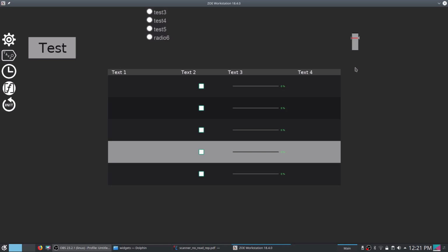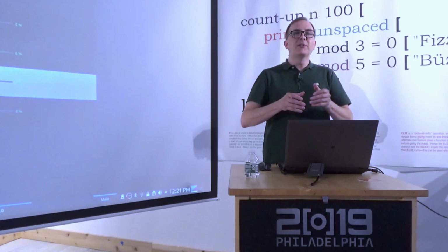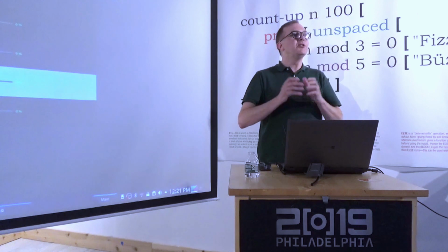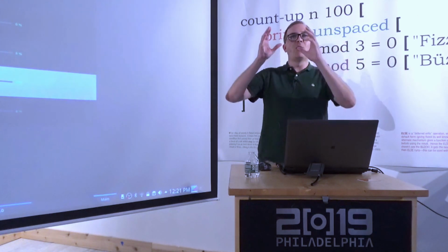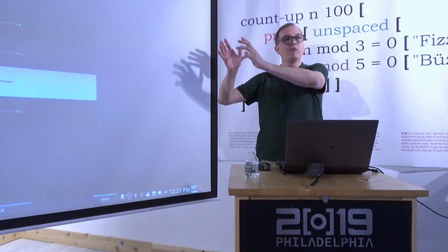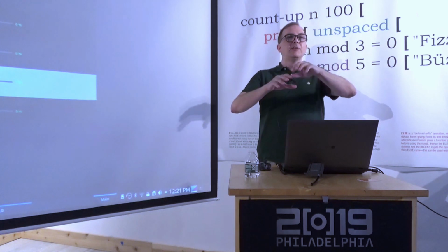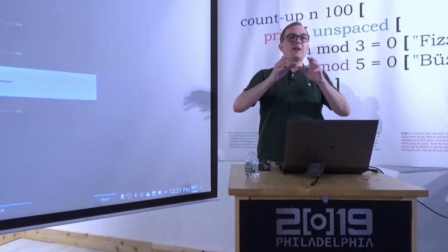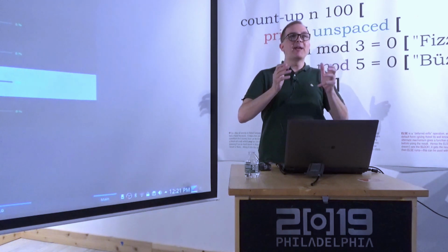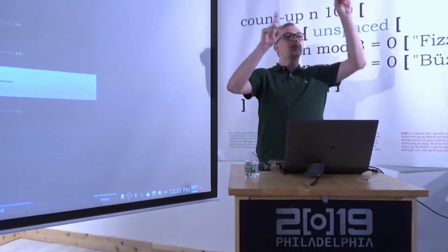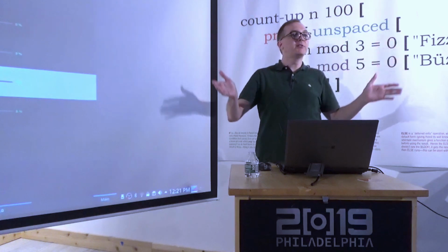And that could also be a separate widget on its own. So you might have these things separated. But another smartness of the widget is it knows what group it's in now. So this conveyor widget, if you want to group it together and have one name for it, like this is conveyor C300, you just have to name it from the conveyor and then select all your pieces for C300, and then group it. And the act of grouping it, when that happens, the conveyor says, oh crap, I got other widgets that are in my group now. Let me go out and name all those widgets automatically.